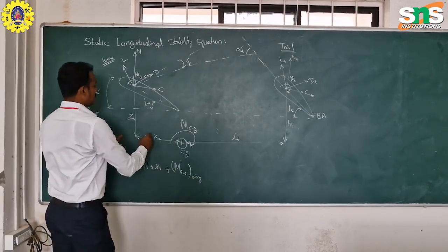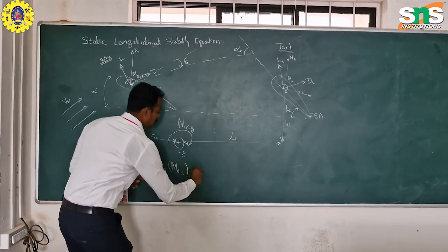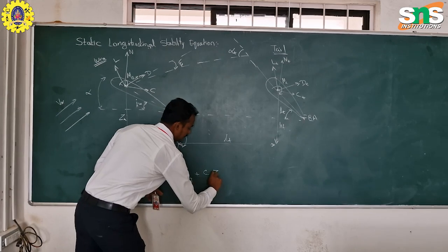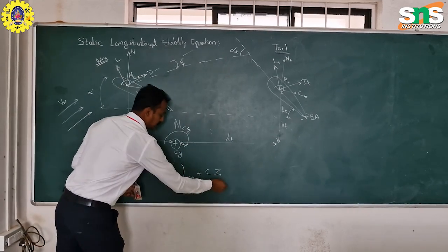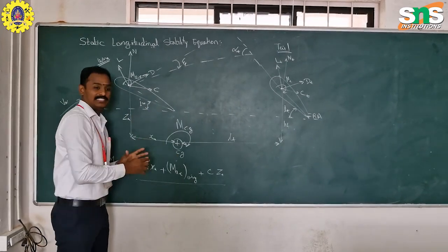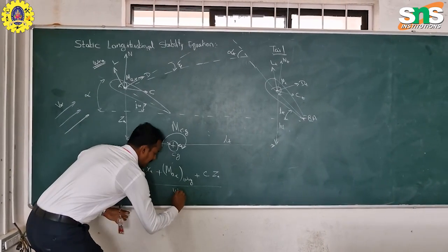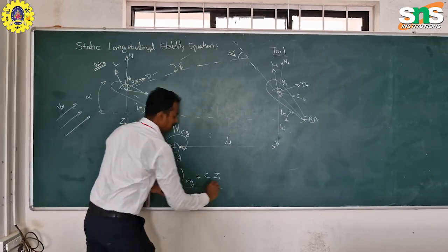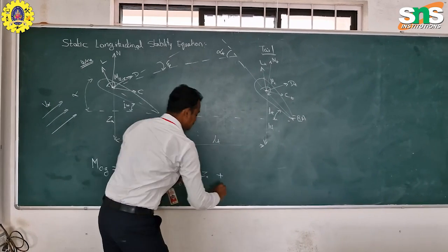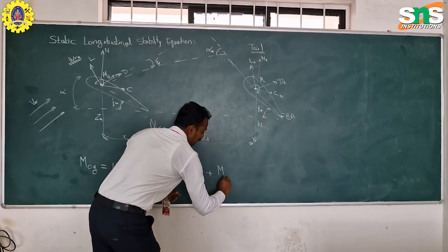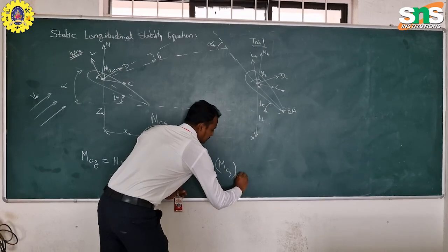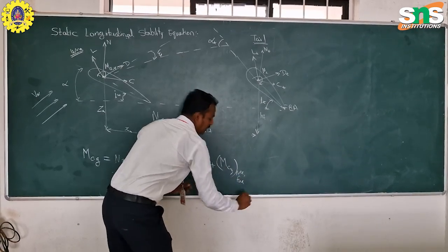Then we take the chordwise force. This is force times perpendicular distance, C times z_a. These terms say where the main wing is with respect to the CG. These terms represent the wing. We will also have some fuselage and nacelle components, so let us take that moment as the moment about the CG for the nacelle as well as the fuselage.